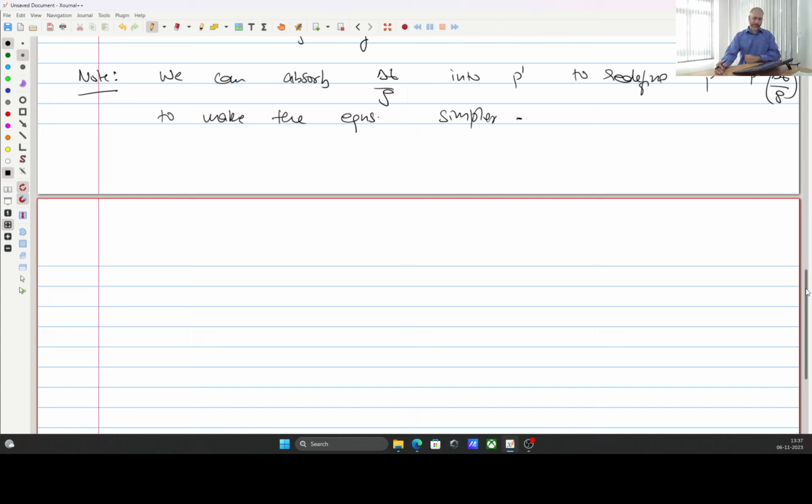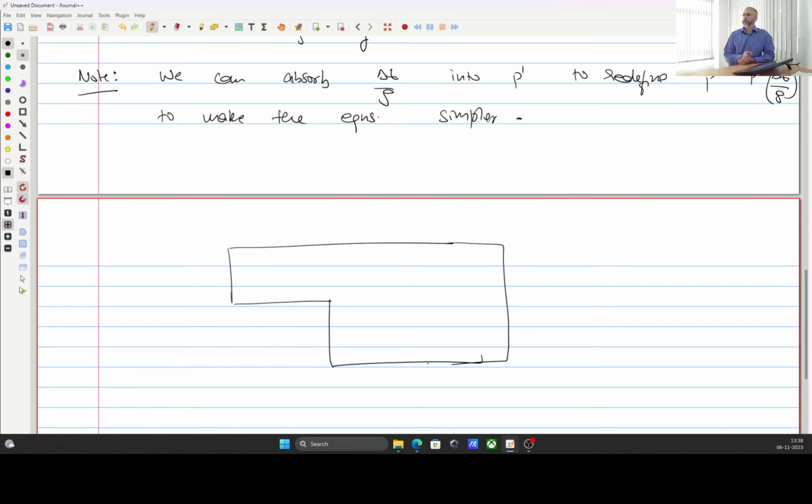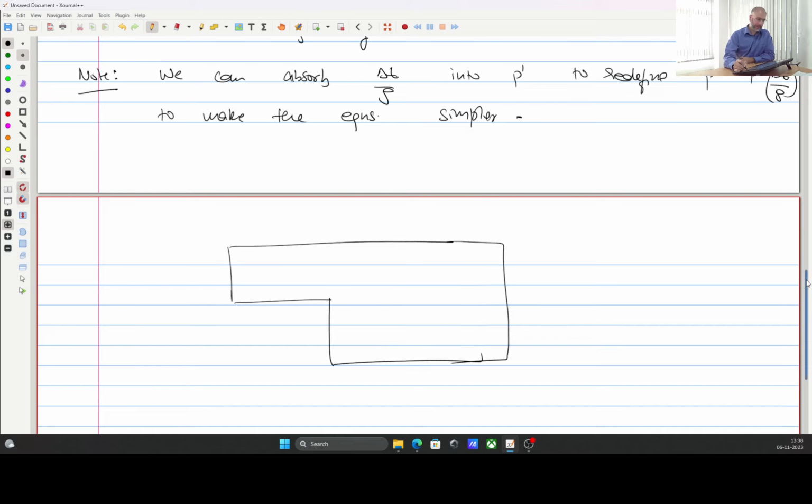For example, in the backward facing step, let's say we are solving the backward facing step problem that we have solved using the stream function vorticity approach in the past. How do we specify boundary conditions for the predictor equation, which are kind of simpler? But what about these pressure correction P prime? What sort of boundary conditions are used for pressure correction? So let's discuss that.